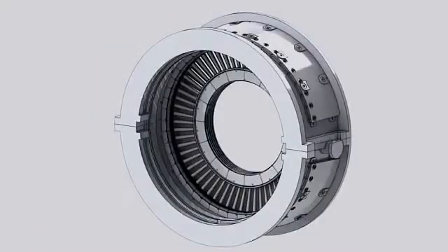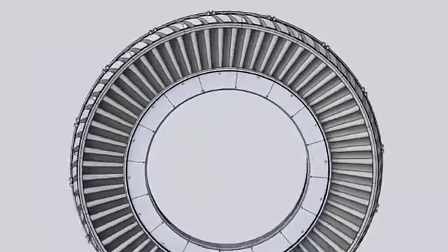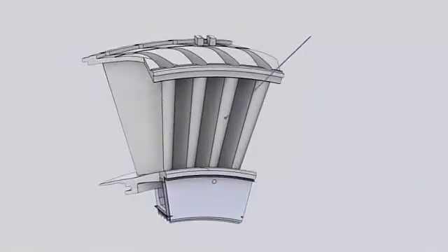The third stage nozzle receives the hot gases from the second stage rotor buckets, expands it further, and directs this flow to the third stage rotor buckets. The third stage nozzle set consists of 16 segments. Each segment contains 4 airfoil partitions. A diaphragm segment is also attached to the inner sidewall of the nozzle. The third stage nozzles are not air-cooled.